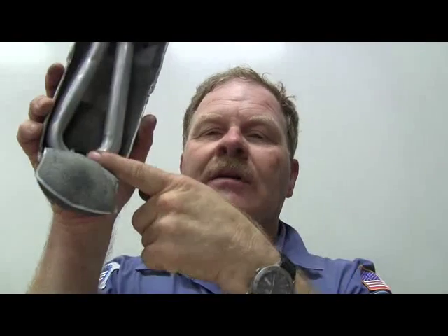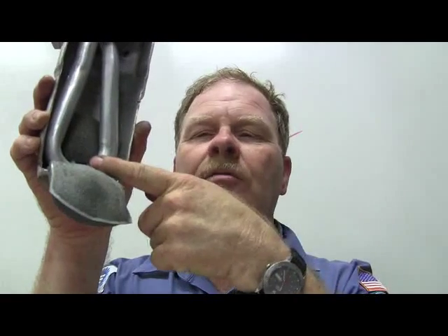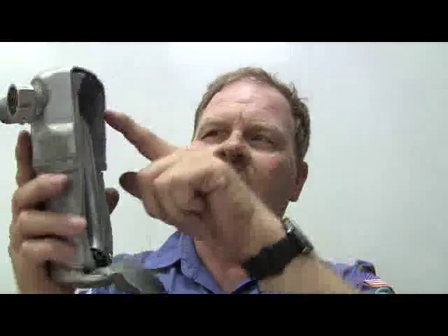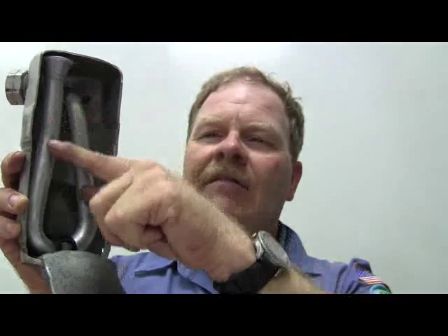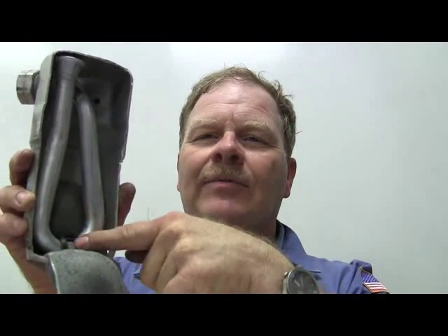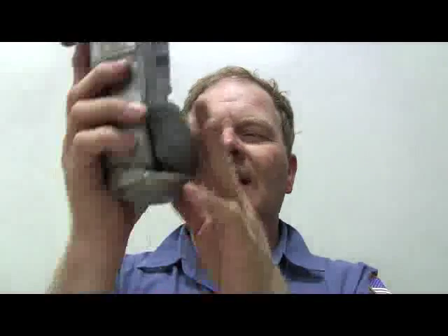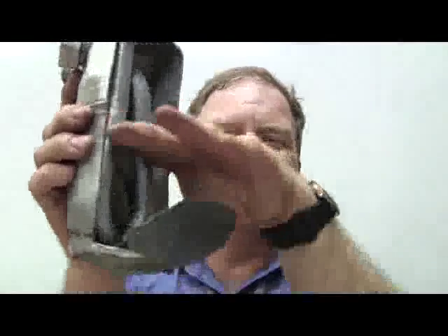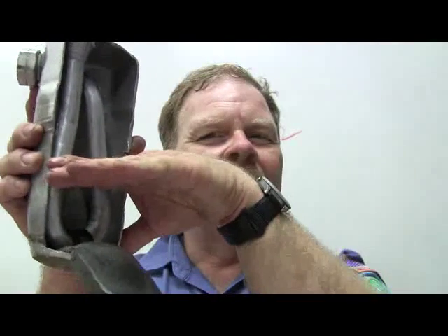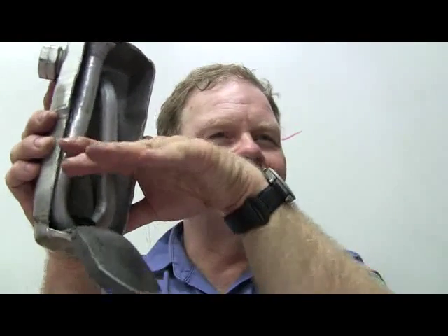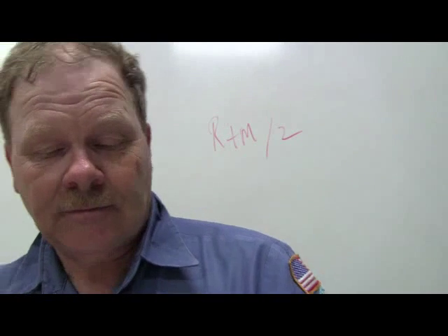But anyway, there's a hole in the bottom of that tube, and it gets oil there. See, it can only pull vapor. That vapor is coming around here, and it picks up some oil, and then it goes to the compressor, and that's how the compressor gets oil. But that desiccant is there to absorb moisture. And this thing's usually about that full of oil and refrigerant whenever it's running. There you go.